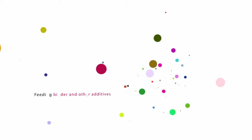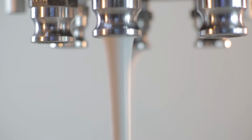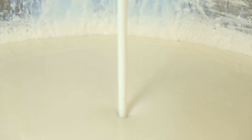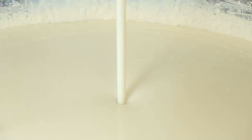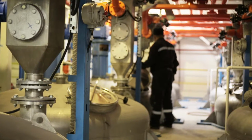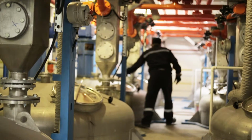Feeding binder and other additives. After the dispersion stage, binder is added and mixed for 5 to 10 minutes. Then, final additions are fed such as anti-foam, antibacterial, antifreeze, and production is completed after 3 to 5 minutes of mixing.